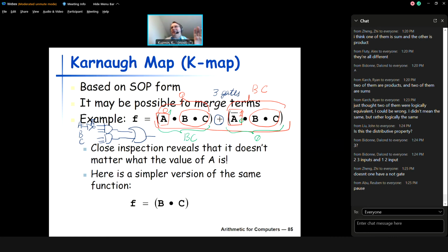So with NOT gates, just look for clues whether you should count them or not. If there are no clues, do count them. The reason is that NOT values can be generated pretty easily and with almost no latency in many cases, and that's why it is often justified to not count NOT gates, because they really don't contribute that much to the latency. AND and OR gates typically have the same latency, which is much larger than the latency of a NOT gate. And quite often in many circuits you already have access to negated values of all inputs, so it literally costs you nothing to use not A instead of A.